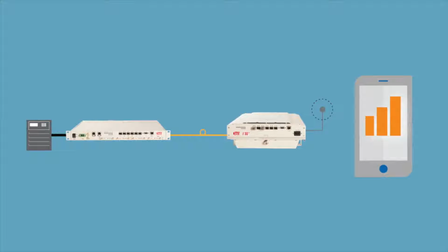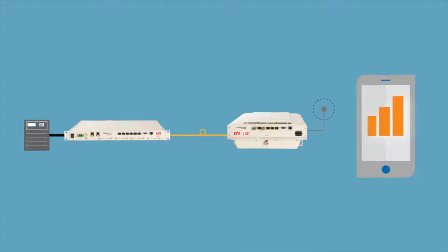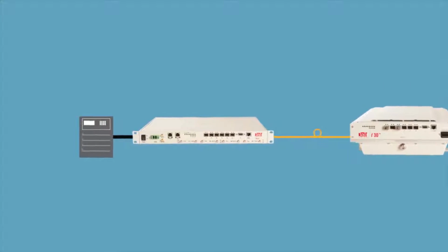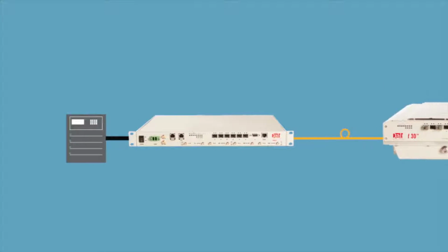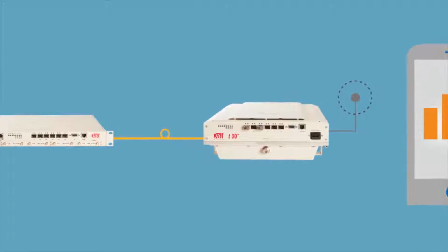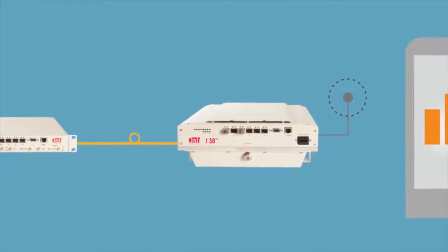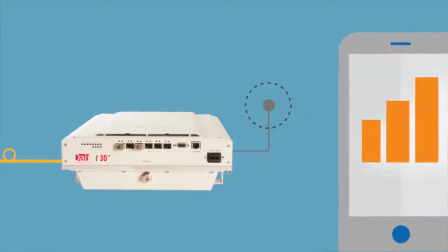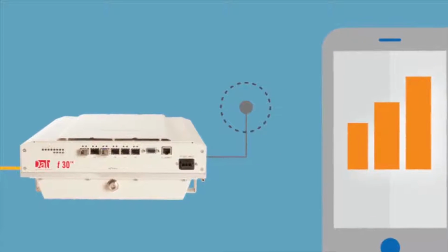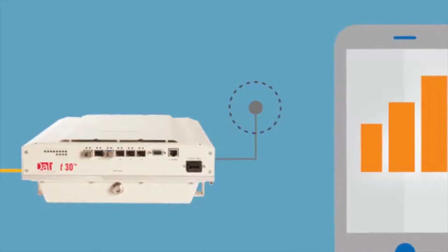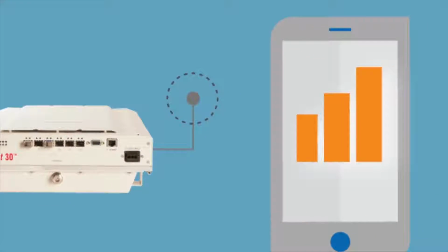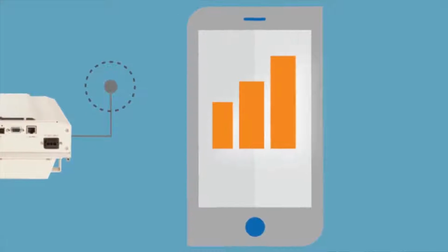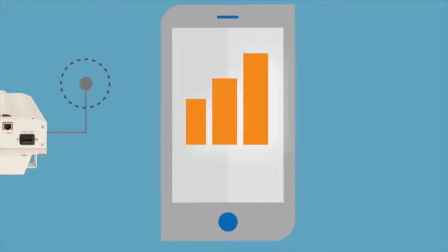Functionality of remotes is as follows. On a downlink path, they're receiving data stream via fiber optic link. That data stream is translated into RF signal inside the unit, and after amplification, filtration, and other RF functions, distributed to single or multiple antennas. And then signal is broadcasted to the user's phone.